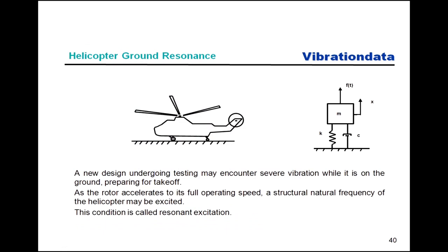Okay, this is something interesting to think about: helicopters. So we've done a base excitation example. That was the Loma Prieta earthquake. We did initial displacement. That was the Pegasus drop transient. And we've just done Tacoma Narrows Bridge, which is aerodynamic instability. Now we're going to talk about an applied force. Anytime we have rotating shafts or imbalance or shaft misalignments or things going on with bearings or whatever, those types of machinery vibrations are actually applied forces.